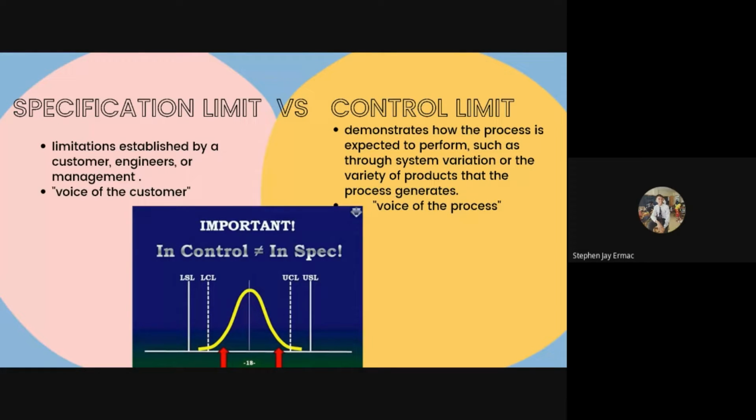benefit of the product. And these limits also are often but not always symmetric. If your part falls within upper specification and lower specification, the part will be meeting your customer expectation, but if it falls outside this range, it will be rejected. It is also used to determine the process capability and the sigma value. So in summary, the control limit talks about the process while the specification limit is all about the customer's requirements.